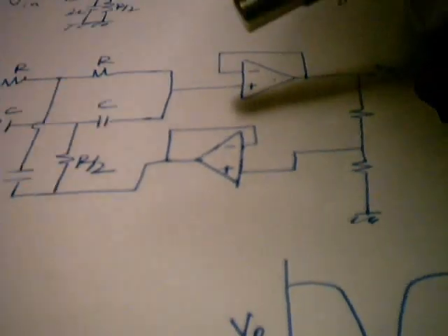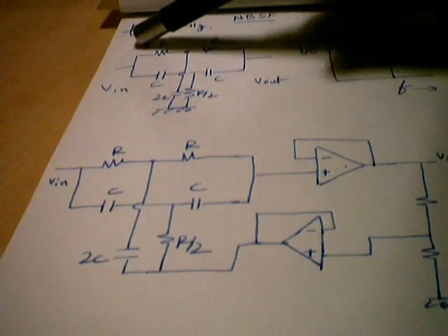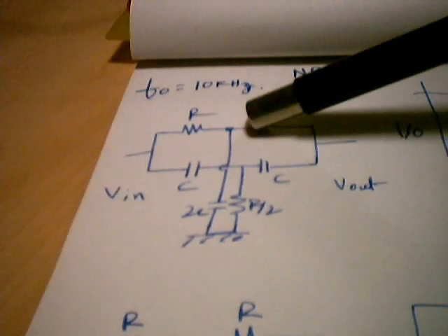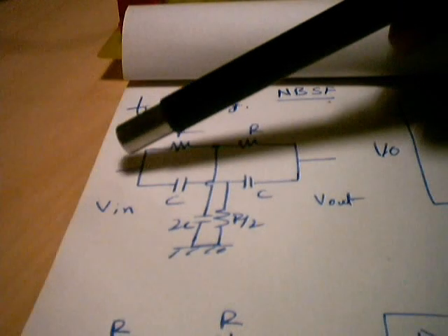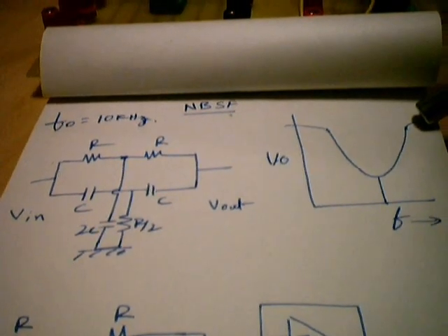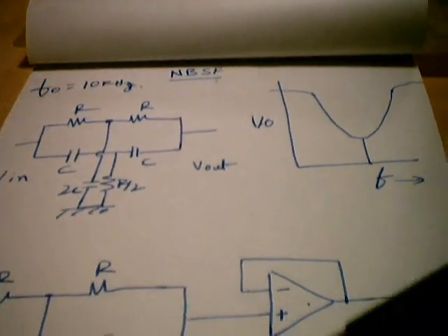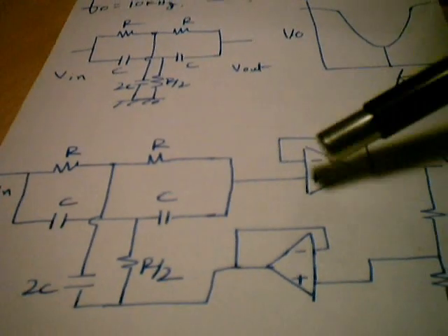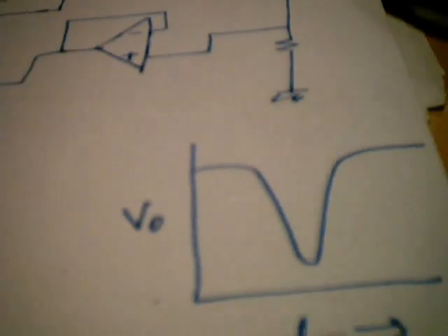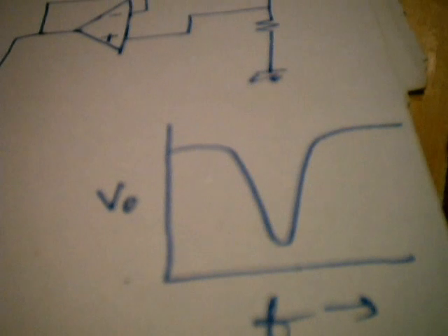Suppose you are having any problem in the output, the first thing is to rig up this circuit and ensure that you are making proper connections using this twin-T circuit. If you verify the input-output relation, you will certainly have the band stop action. Then you can go for the next connection, which will reduce the bandwidth and increase the Q factor of the band stop filter.